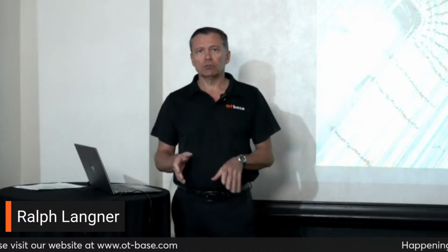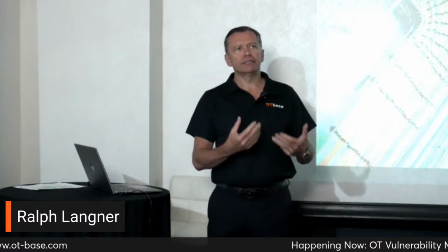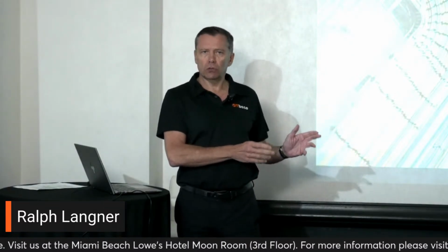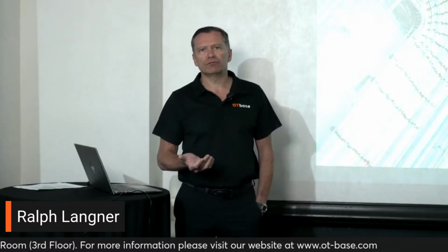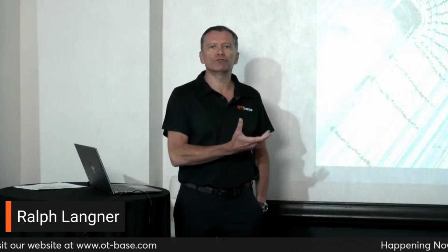And that also means you will not be able to properly identify which vulnerabilities affect your installed base if you don't have an accurate and comprehensive OT asset inventory. In order to get to that inventory, your anomaly detection won't do you a lot of good, because usually what you see in passive identification is that the granularity of the information you're getting from the devices is not sufficient. And that's the simple reason why in some ICS detection products that also expose vulnerabilities, you see a probability associated with that CVE.